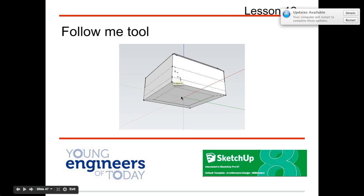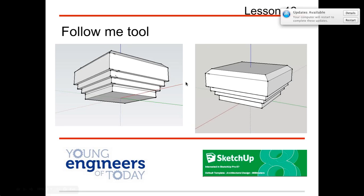And what I was talking about before with how it can save you time is if you're making almost like a staircase shape, like here, my shape, I made this staircase, and then I did the Follow Me tool around the edges, and created this really cool effect that would have taken me a really long time to create all of those boxes and stack them, or use the push pull tool and draw kind of squares on top of that. Instead, it did not take me long at all to just create that shape and then use the Follow Me tool.